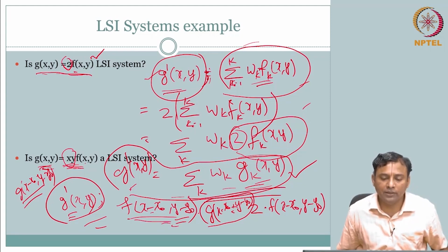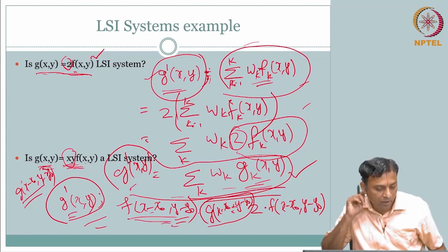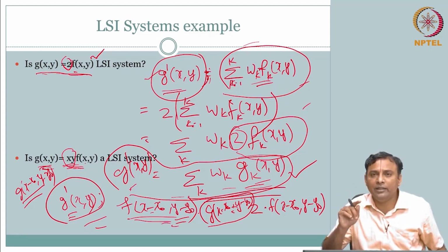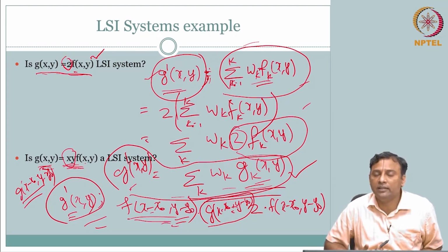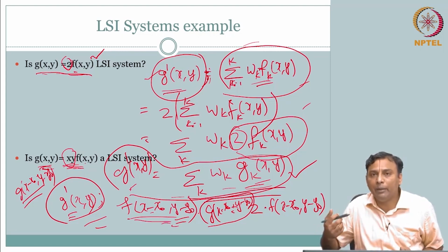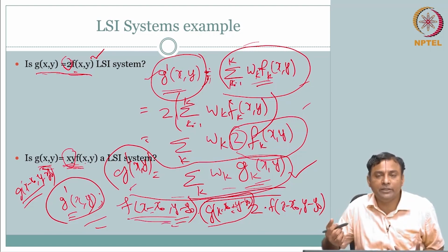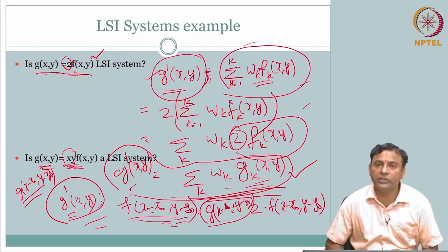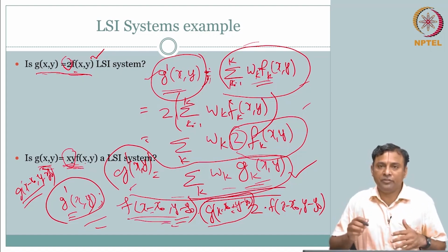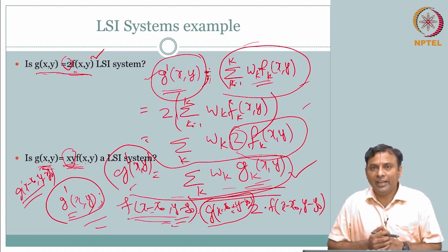So, we will end up using a linear shift invariant system for our imaging system. I think the message should be very clear that it is not just because we can solve all this and get some easy mathematical traction. It turns out that this simplification does not really take away the ability to model a general imaging system. At least for most of the imaging systems that we are going to cover here, for the most common usage, I think linear systems theory is also physically very representative.